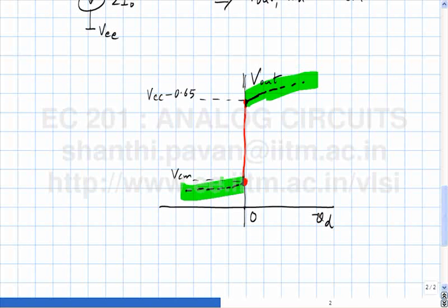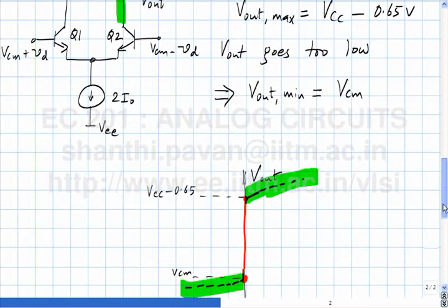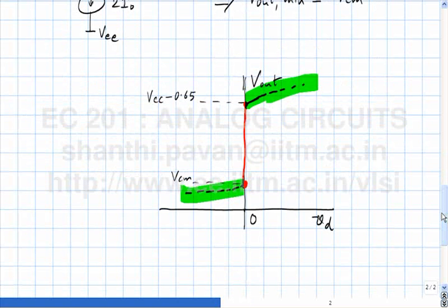In the bipolar case it's a little more tricky because when the VCE is very small, when the transistor becomes saturated, in other words, the collector goes below the base, a significant part of the base current actually gets into the collector also, making the analysis a little painful, which is why I avoid it.